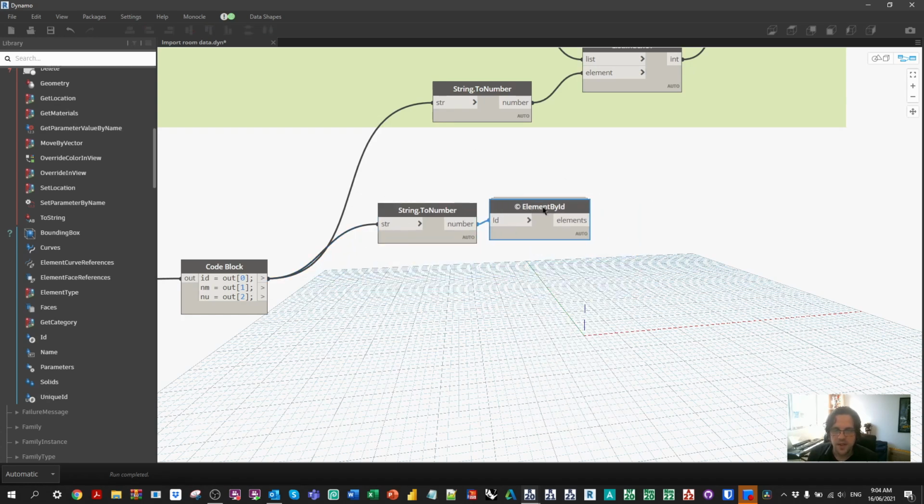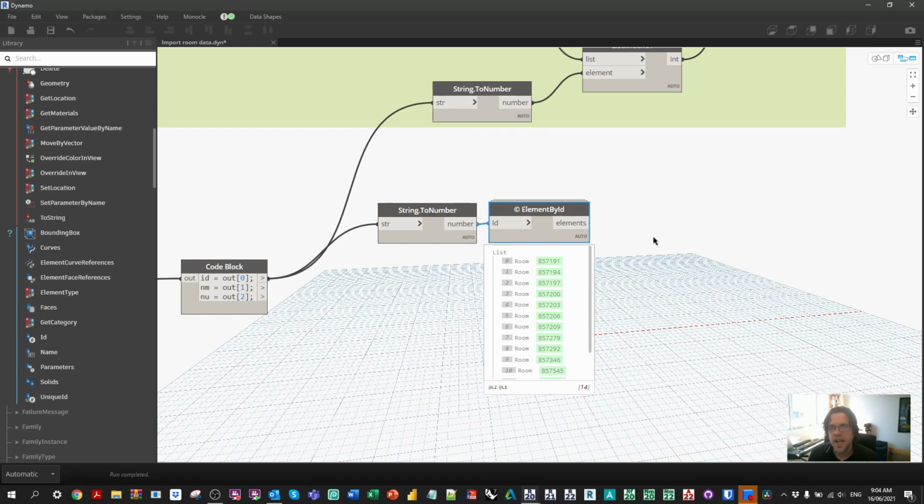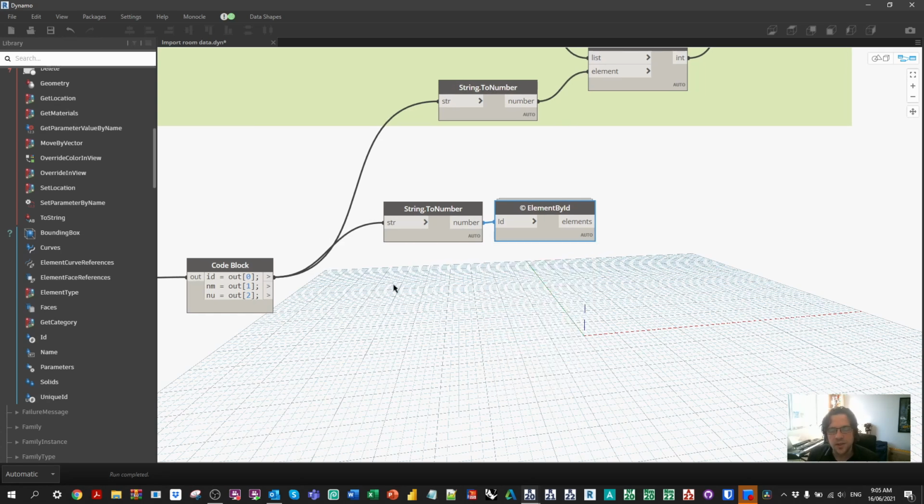From here, say you find some elements aren't matching. In this case, you may need to do a filter by Boolean mask based on an is null condition for the rest of your data, to make sure that you've cleaned out any data that isn't actually finding a match. But hopefully in most cases, every piece of data should find a match if the rooms are still there.